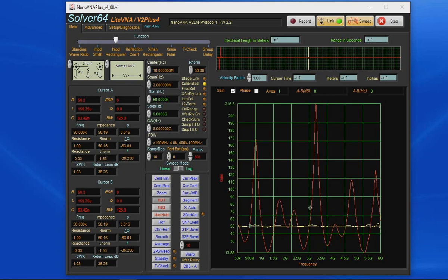Now again, this software has had gating for quite some time. What had happened is I recently watched a video from Copper Mountain Tech. Of course, they produce VNAs, and they went over this time gating feature, and they talked about how they were doing this windowing function. And I realized what I was doing was physically zeroing out this data. Again, you can do that, but it causes a disturbance when you run the FFT across it. So while it definitely made an improvement in the measurement, it was also causing these additional disturbances. So I changed my software to add this filtering instead of this aggressive zeroing.